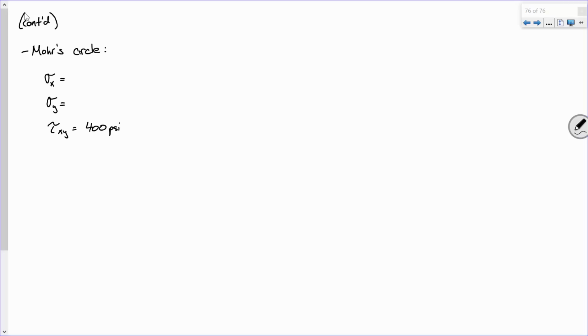Now, our bending stress, what was our bending stress? We just did it. 900. Now, pop quiz. Was that bending stress in a compressive nature or a tensile nature? It was compression, right? Remember, it was above the neutral axis, positive bending. That's compression. So I propose one of these normal stresses needs to be a compressive stress of 900 psi.